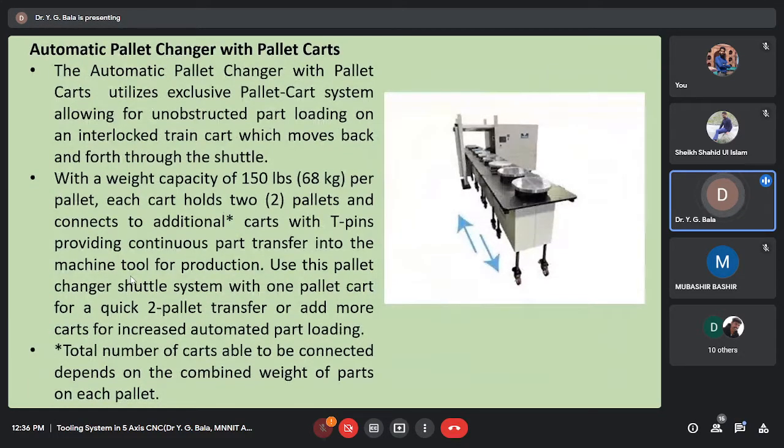Another type of pallet is pallet carts. Here it is like a trolley. Either manually he can pull out this pallet to the workstation, or this trolley type can work with AGVs or some control elements so that it can reach the position of a particular workstation. This type of arrangement we call carts. It will have both forth and back travel, to and fro motions. Based on the programming also we can bring out our pallet at a particular station and accomplish the machining part.